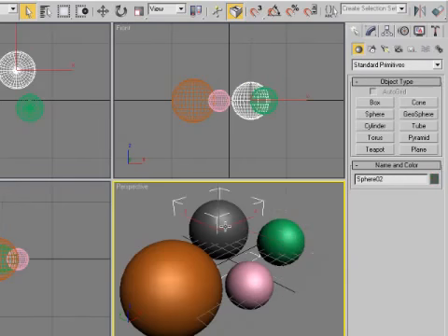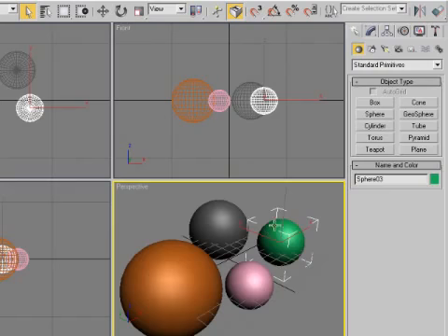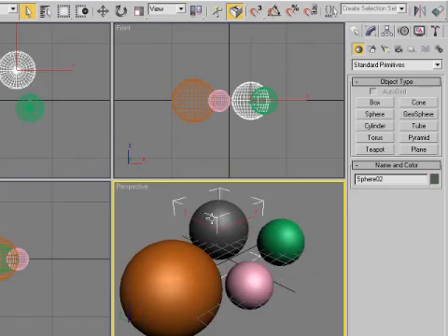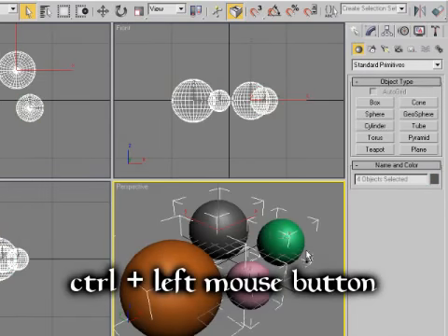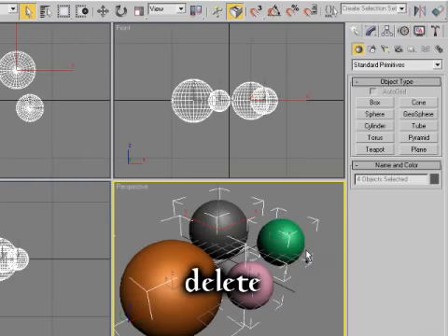And you can go to Selecting Objects. If an object is selected, it'll be bracketed, or in a wireframe view, it'll be shown in white. To delete objects, just select it. You can Control-click to select multiple objects, and hit the Delete key on the keyboard.